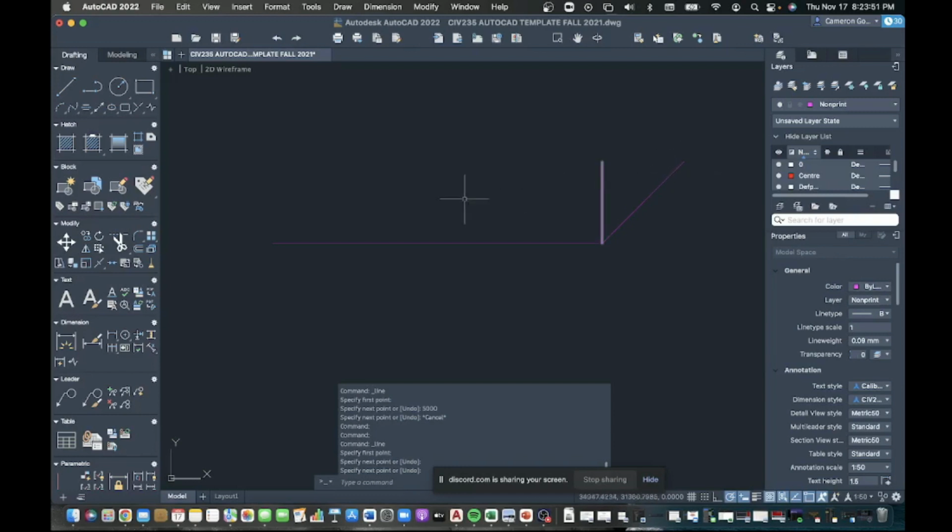What this can do here is create a 3-point arc. So how we're going to do that is we're going to do a line. I'm going to select 3-point arc first, second, and third point. Click enter. There we go. That's the top of our bridge portion there.